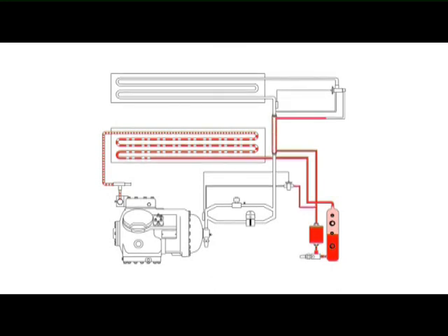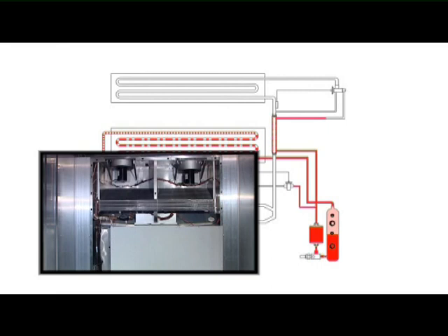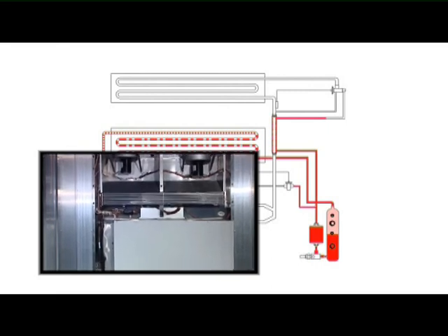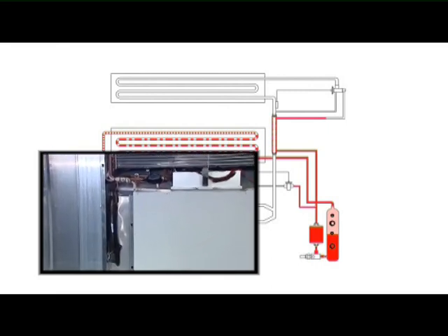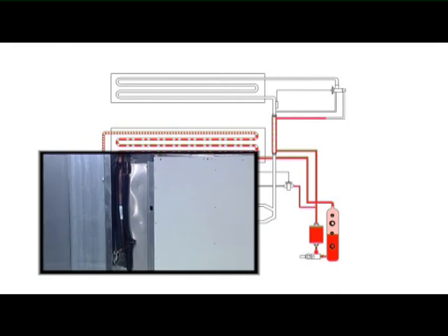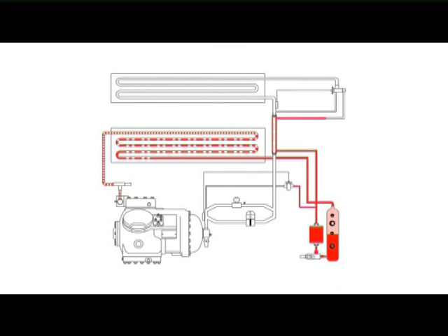The high pressure and high temperature refrigerant will reach the heat exchanger. In the heat exchanger, the high pressure and high temperature refrigerant transfer heat to the low pressure and low temperature vapor, returning to the compressor. This will improve the efficiency of the system.